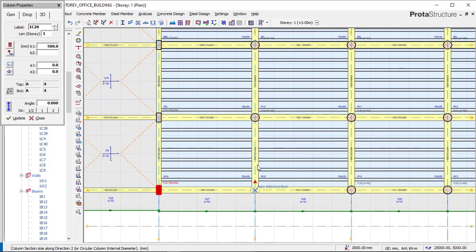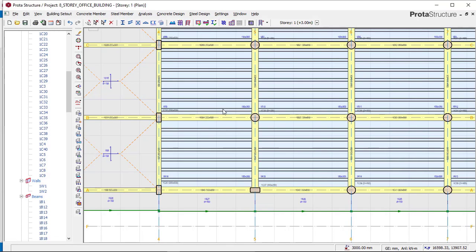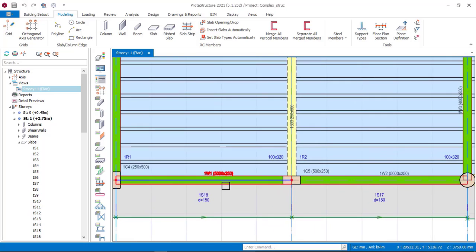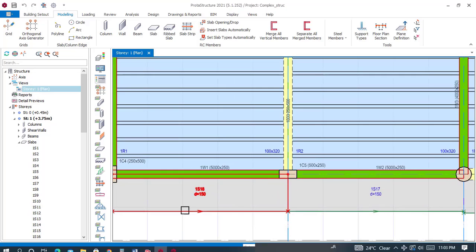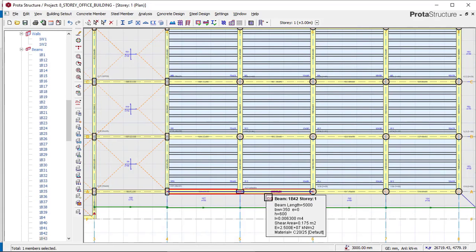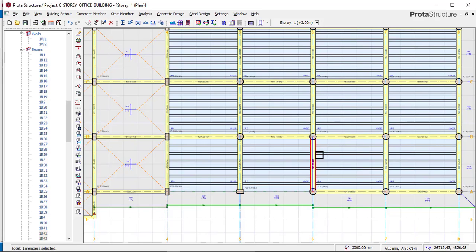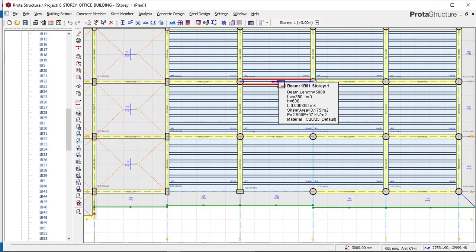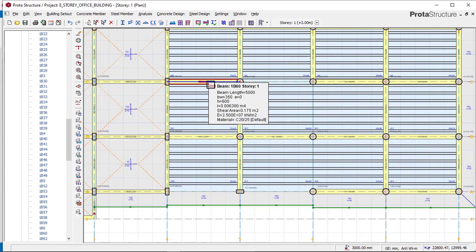You can see that. Then right now, we can go to confirm what we have here just now. If we go to this place to check the size of this wall, you can see it here is 250. So we can now delete all the beams that we have on this other place. Delete this beam also. Delete this beam, and then delete this beam also, because we don't have that beam there. Delete this beam also, because on this place we have a concrete wall on this other area where I'm deleting the beams. So delete this beam also.